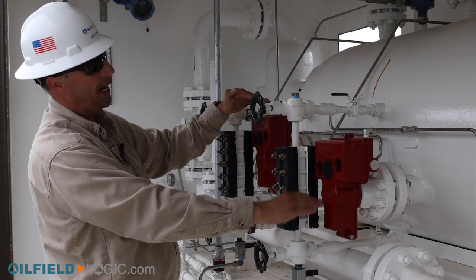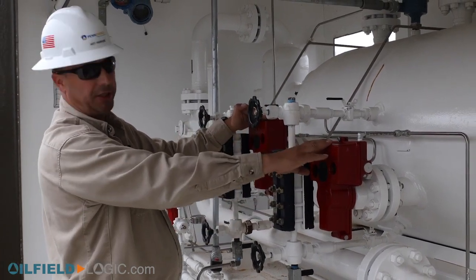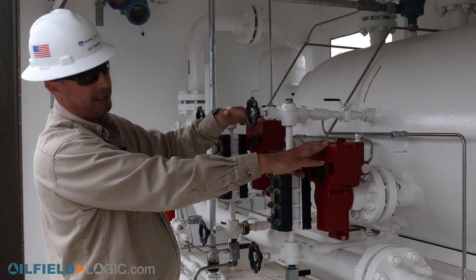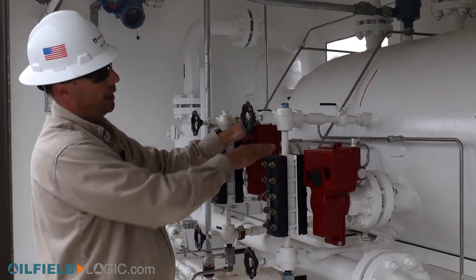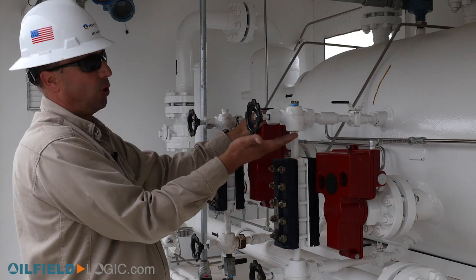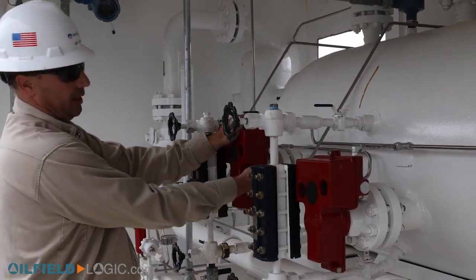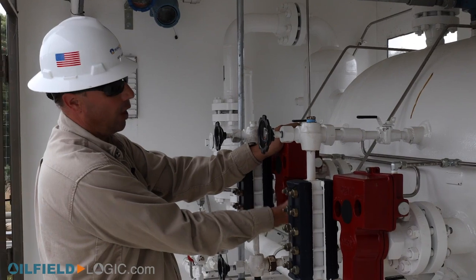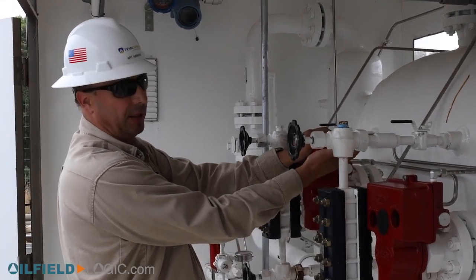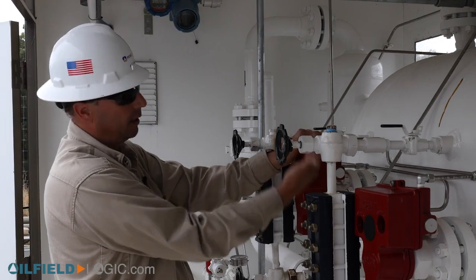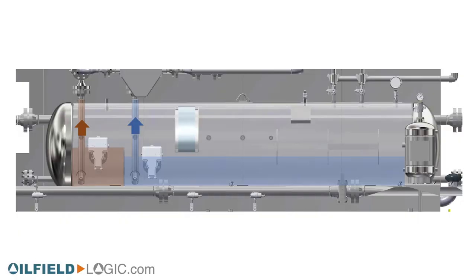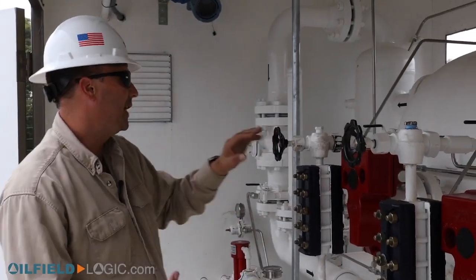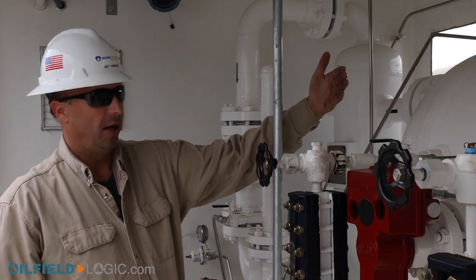Downstream from there would be our condensate stage, second stage of the 3-stage unit. You can see that's a little bit higher compared to the water stage, and that's because that oil will be settling in on top of that fluid, and by what we call a weir plate, that'll spill over the weir plate, start to fill up this stage for the oil. And same as the water, when that float gets to the point where it'll open and lift the pilot in here to create that dump valve to open up, and just by a difference of pressure, that'll be removed from this separator.